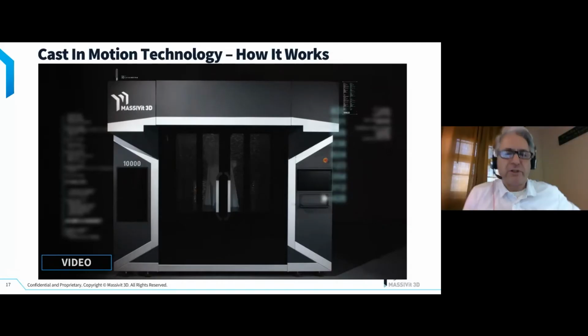Yeah, that was pretty good. Okay, a couple things I saw there that I didn't mention, and they obviously articulated it a lot better than I could, is you can see what looks like support material on the outside. Those are stiffening ribs. So when you have a large part that may be somewhat flat or just large in nature, we're putting stiffening ribs in there to help the accuracy of the shell material for the casting process.